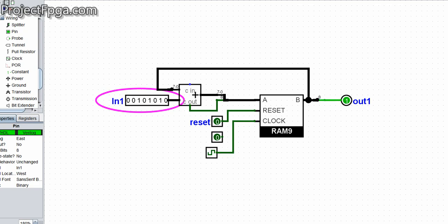You can see. Now let me make it all 1. You can see it is outputting 1 more often because the values that I'm sending in are very high, so there is so much overflow. The overflow comes quite often. So let me reduce the input so you see now it's low. Before it gets a 1, it's going to take time to get a 1. So this is the typical delta sigma modulator. This is the modulation actually. Let me stop it at this point.